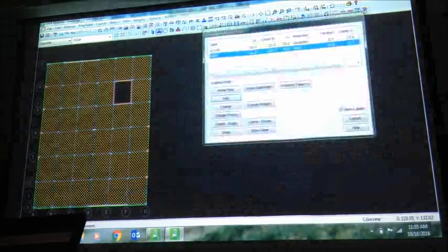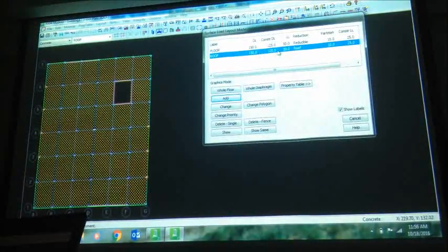First floor, I'm not going to change any load. Only thing I'm going to do is add the foundations on the first floor. If you add foundations on the typical, that's also fine. It will actually show the foundations at the bottom of the first floor. What's the load for the roof surface again? Roof surface: dead load is 100 and live load is 20 PSF, and it is roof live load, which means it's reduced according to the roof equation.